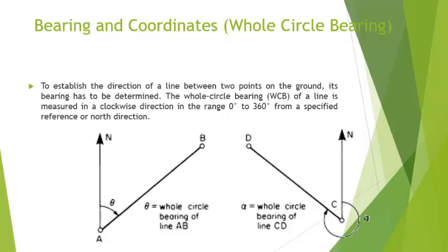If the starting point of traverse has only 2 boundary marks, then the orientation will be corrected using sun or solar observation. And if the starting point has 3 boundary marks, then the interior angle can be checked and compared with the interior value in the certified plan.